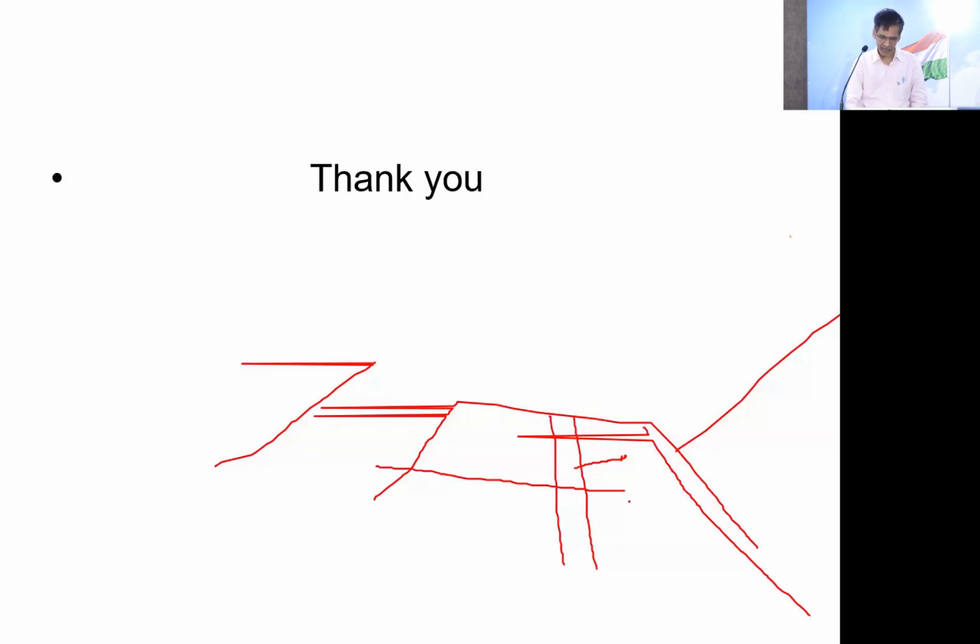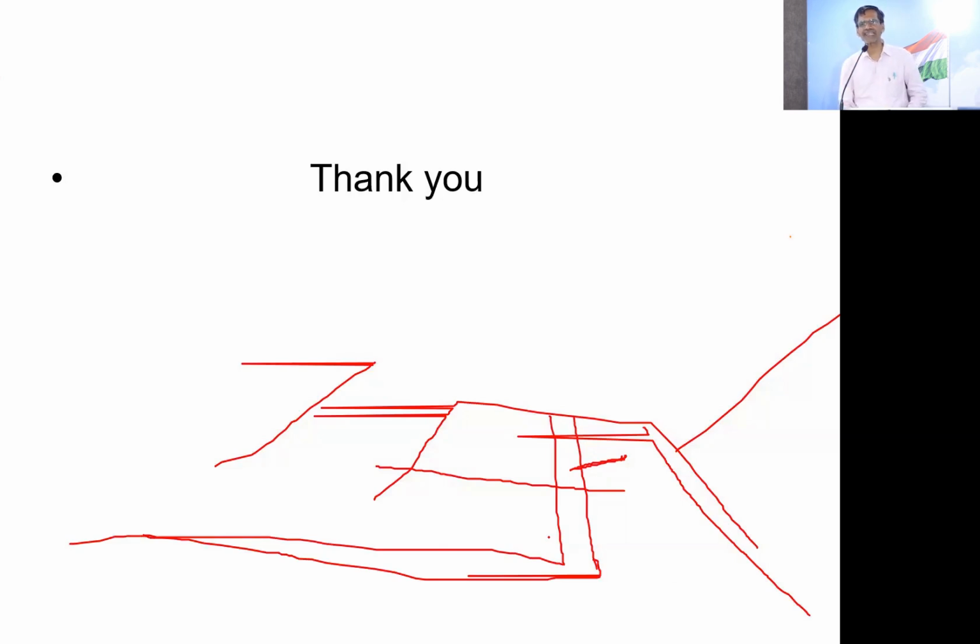With this chimney or drainage layer, whatever you call it, once the water reaches it over a close distance, it can quickly pass through and go out. So that is the advantage you get for keeping the embankment dry.